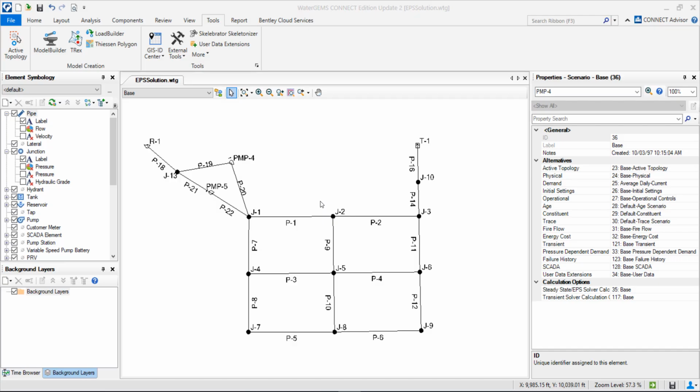One of the solutions is this one, that we call the tank control scenario, where we have water coming from reservoir number 1 and pumped to the network, where we also have an elevated tank downstream. So this tank is also able to supply the distribution network by gravity when the pumps are turned off. We have then defined another scenario